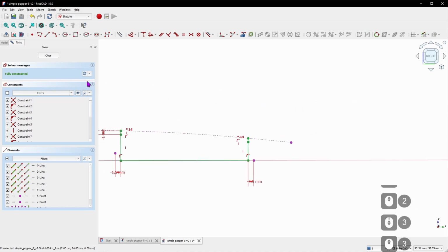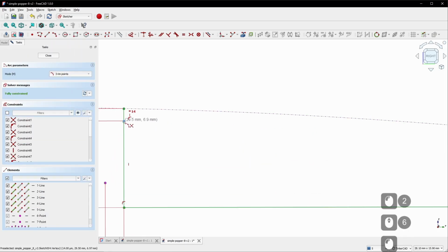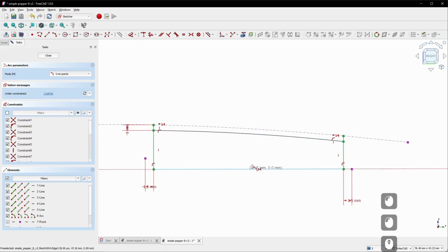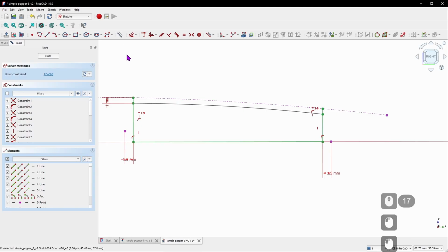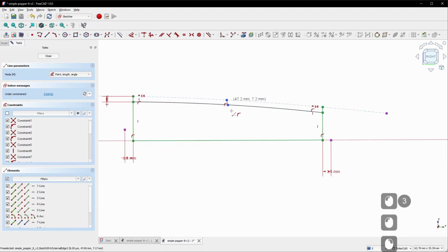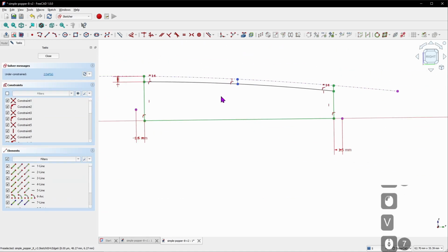We're almost done. I just need an arc. I will create an arc by 3 points and drop it on that line and that line. And then I want to constrain this, so I will go ahead and drop a construction line between that arc and that B-spline, external geometry, and make it vertical as well. And before I set its height, I'm going to set its horizontal distance. Otherwise, it'll jump on us. Oops. Let's do Control Z. Grab that point and that point.